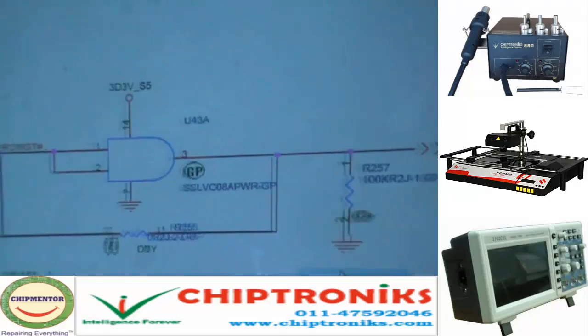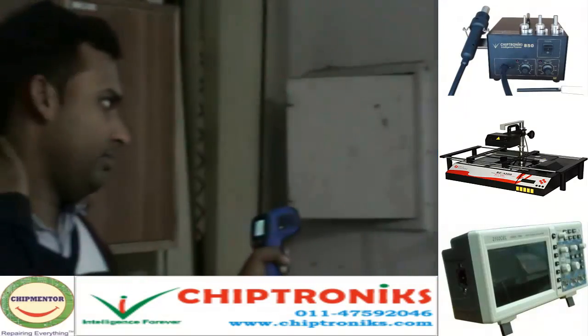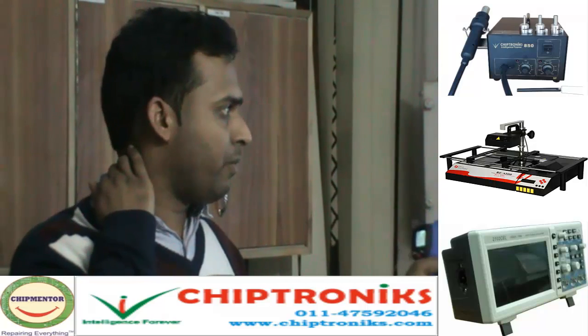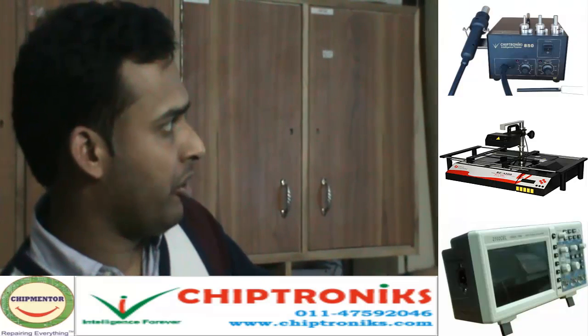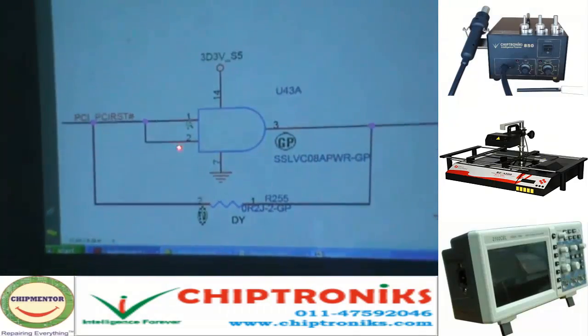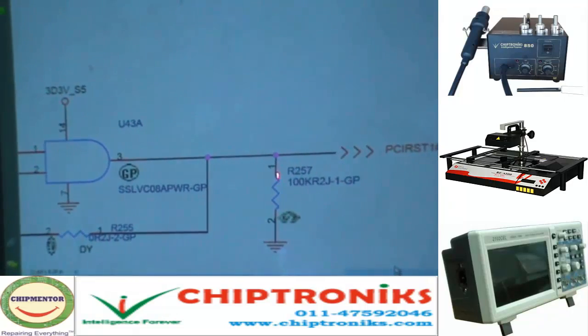Why is this done? This is done so as to make this PCI_PCI_RESET the same as 3.3 volt. If you measure with a digital multimeter, sometimes this voltage may not be 3.3 volt, but we have to make the output 3.3 volt. So we have used an AND gate over here. This 3.3 volt input signal will go to the output if any signal is coming from here. So you can measure 3.3 volt over here across this resistor.